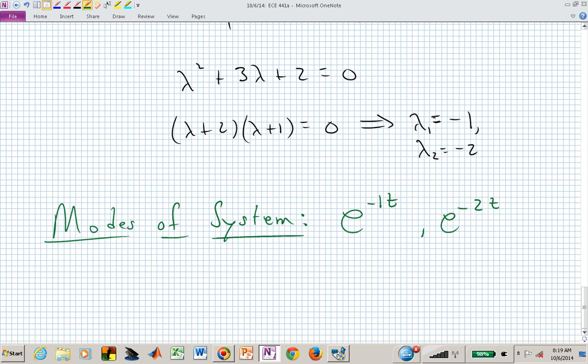If the poles are in the left half, they have some exponential decay to those oscillations, and that's then going to give you the shape or the modes of your system response. In your homework problems, you are looking at some of these initial condition responses. You're exciting your system by putting variables at some initial value and seeing how they decay with time. And they decay based on these exponential decay concepts.